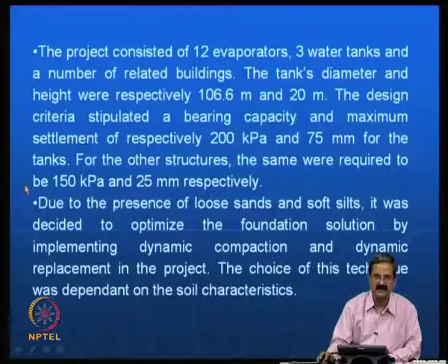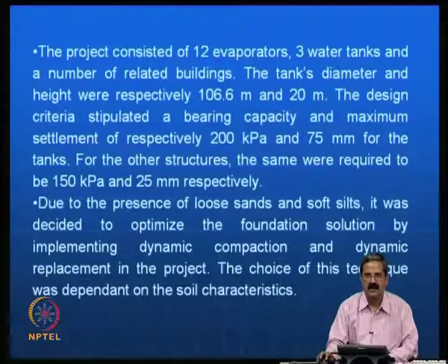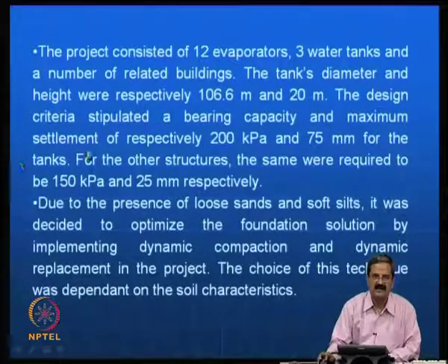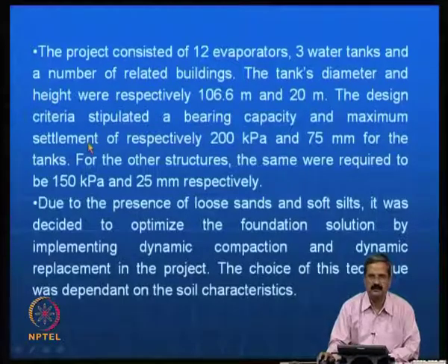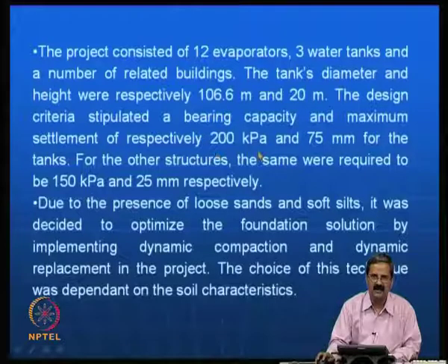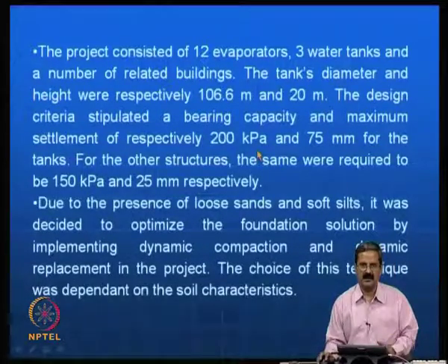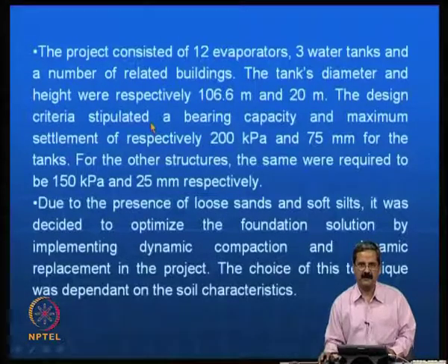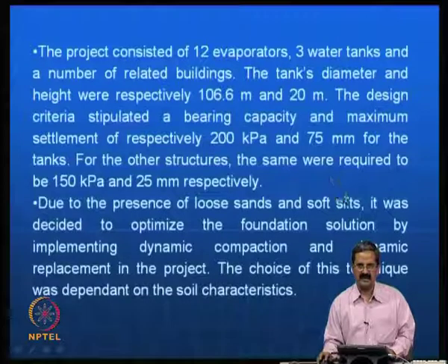See, even on very soft soils you must be able to construct water tanks in villages, for example in many of the coastal areas in India. So the bearing capacity requirement could be like this, and the 75 mm settlement is valid there also. So you need to really improve the soil using some sort of ground improvement technique. That way one can see that this is a very stringent requirement.